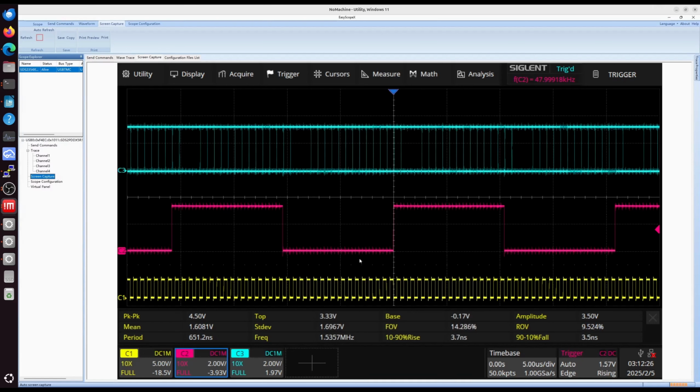So right now the very bottom signal down here is the bit clock. That's kind of the main clock driving things, coming over to the codec board. This right above it is the left-right clock, so that should match roughly the frequency I'm trying to sample at. And this top is the actual data that's being brought into the codec from my Zynq board.